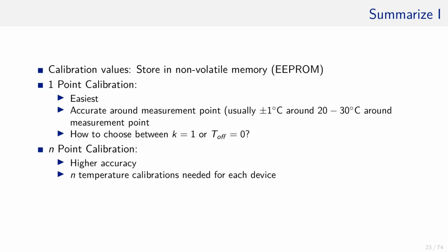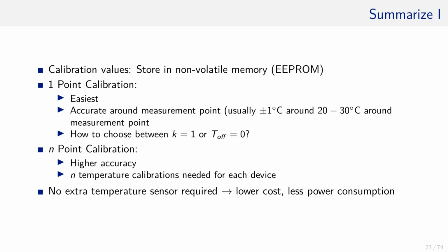Higher accuracy can be achieved with more calibration points. Imagine you have infinite measurements. Therefore, you are aware how the green snaky line looks in the entire operational range of the ATmega. But usually, there are only a few points available, so any other point needs to be guessed. On the upside, once the hurdle of calibration has been taken, the developer is rewarded with a low cost and low power temperature measuring device, since it is already present.